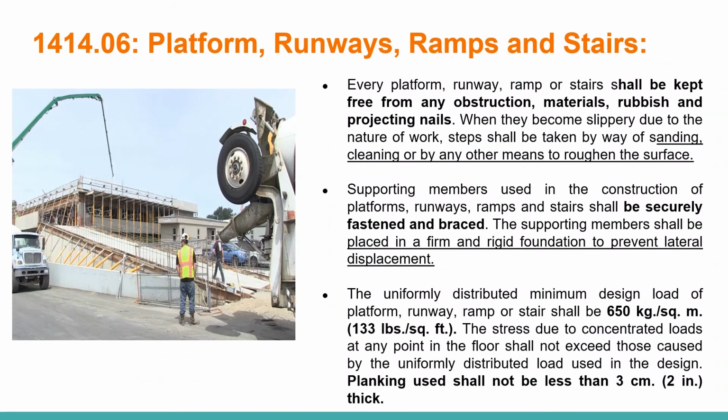Every platform, runway, ramp, or stair shall be kept free from any obstruction, materials, rubbish, and projecting nails. When they become slippery due to the nature of work, steps shall be taken by way of sanding, cleaning, or any other means to roughen the surface, and they should be securely fastened and braced. The uniformly distributed minimum design load of the platform, runway, ramp, or stair shall be 650 kilograms per square meter or 132 pounds per square foot, and planking shall not be less than 3 centimeters or 2 inches thick.